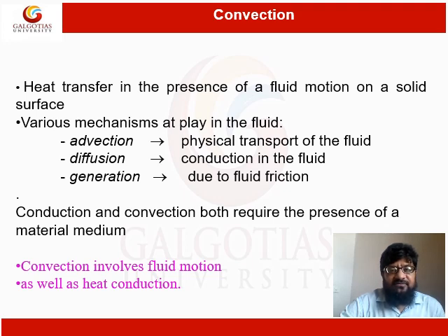The various mechanisms which play a role in convection heat transfer are advection, diffusion, and heat generation. Advection is the physical transport of the fluid. By virtue of the movement of the fluid particles, heat is transferred from one coordinate to another.